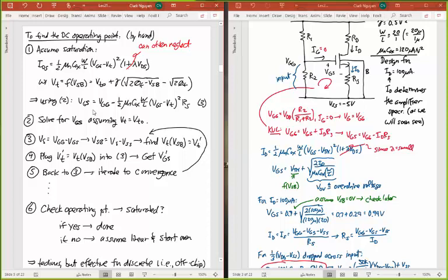Okay, so Kieran is answering that question correctly. Why do we assume saturation? It's because we want to maximize the drain current. That's the area where you're able to get gain out of the transistors. You won't know that until we go through small signal analysis and a little bit more. That's coming. You'll understand that very soon.